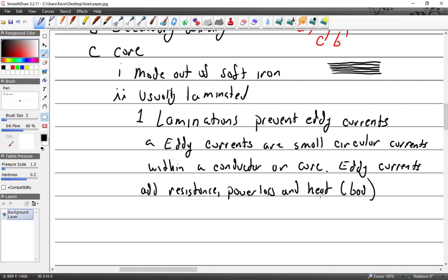Is that for determining the thickness of something without having access to the other side? Is that for the eddy current? It can be used for that. It's not necessarily what it is, but I've heard it used for that. You can determine the thickness of metal. You can find small cracks.